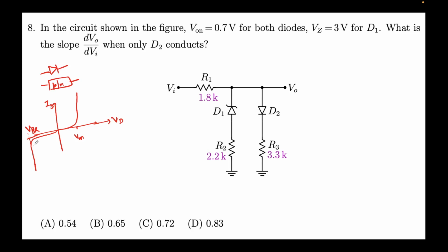The advantage, if we operate in this region, is that it can support large amounts of current, a few milliamps, tens of milliamps, and the voltage will not change. If the device is not burnt, you can also use it in the forward direction, but we need a special diode.